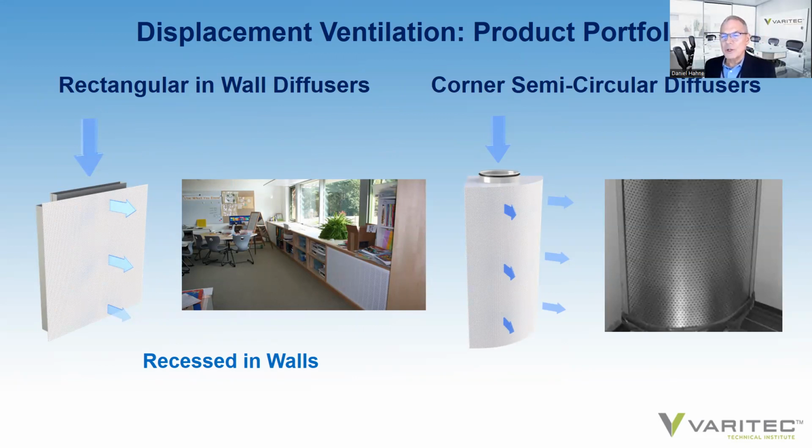One way to understand how many square feet of diffuser face area are required for a space is to calculate the amount of air necessary to meet the space load in the occupied zone, and then take that amount of air and divide it by 40, and that'll give you the square footage of diffuser face area to evaluate architecturally and how that might be installed within the space.